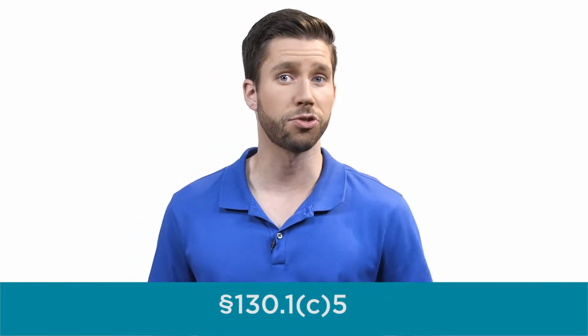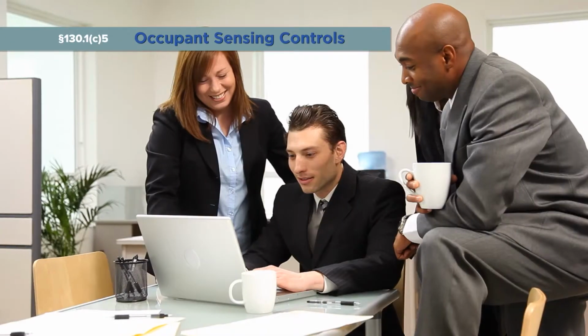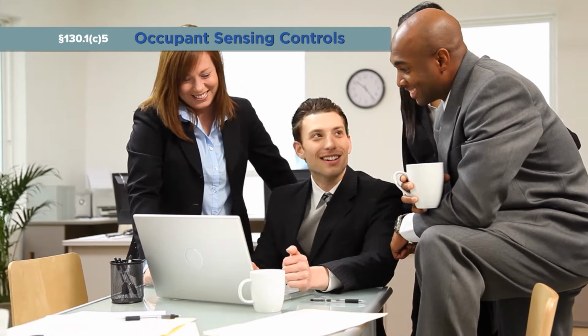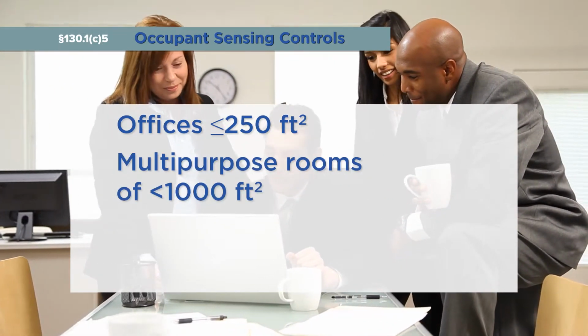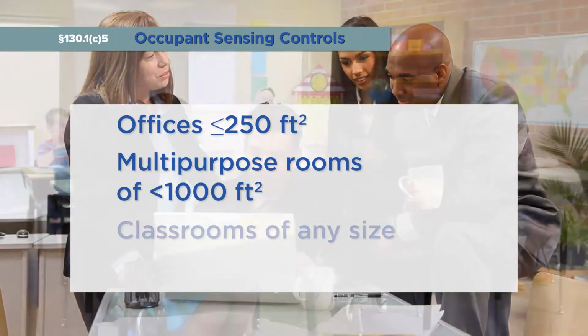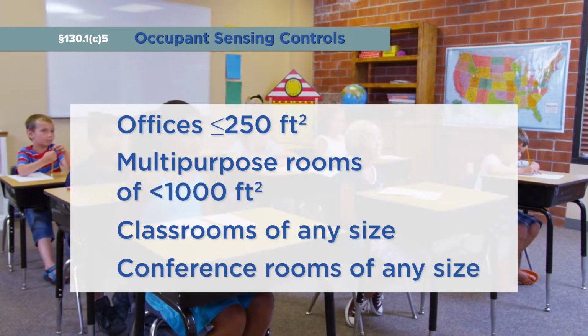Under the energy standards, occupancy sensors are required to shut off all the lighting in certain types of spaces. We'll review these requirements now. The energy standards require occupancy sensors to shut off all the lighting in offices 250 square feet or smaller, multi-purpose rooms of less than 1,000 square feet, classrooms of any size, and conference rooms of any size.